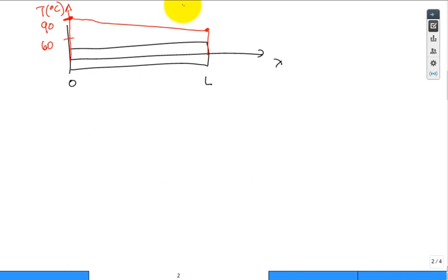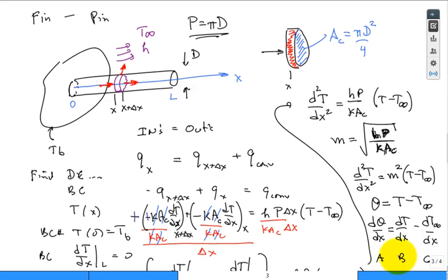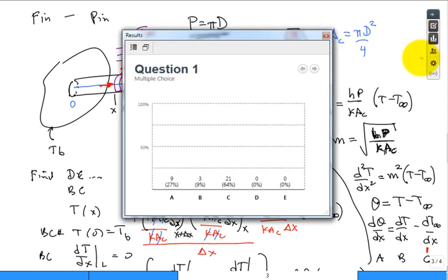And so wouldn't that be where I'm trying to find T as a function of x, right? Well, why is it going down? Because there's fluid cooling it. There's T infinity, and there's h convectively around the surface of that fin. So when I come back here and I ask the question, is it A, B, or C that's equal to 0? Does the fluid temperature change as I'm marching further out away from the base? That's the term that's 0. So C is 0.